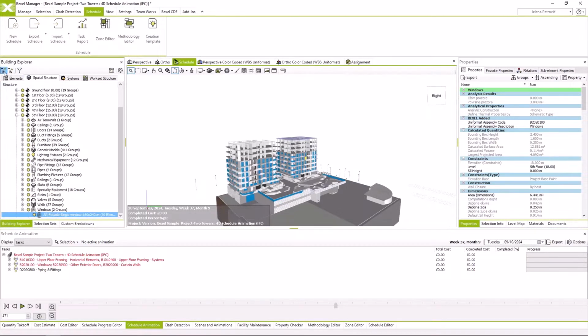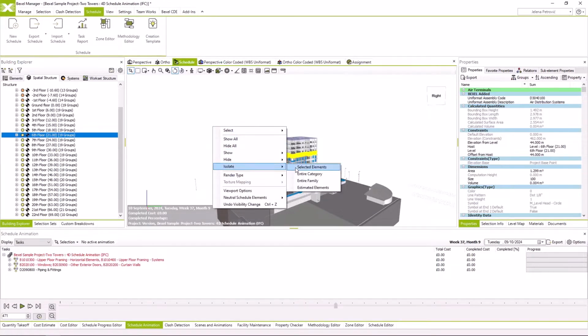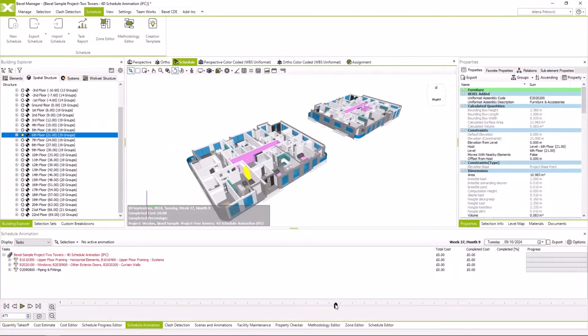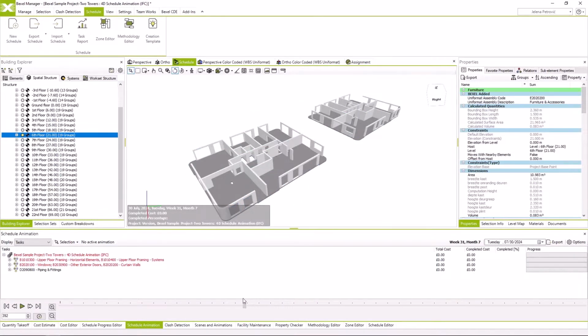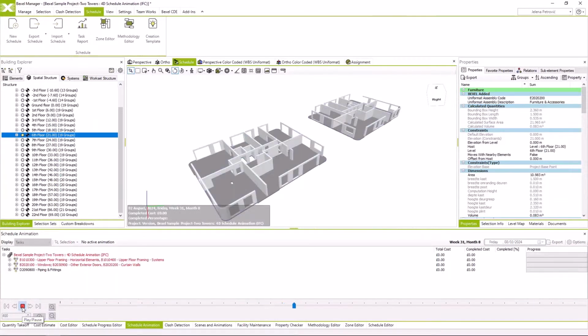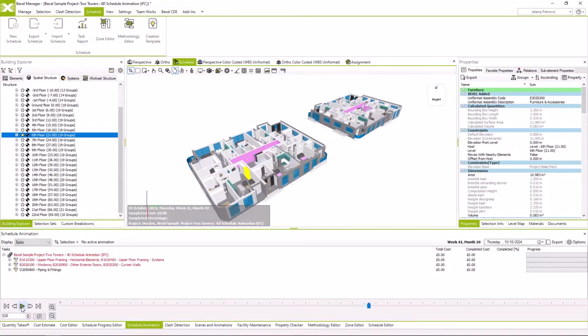Then also, our model is federated from IFC files exported from the Revit authoring tool, so the export settings should be properly defined, or if the export of IFC files is coming from other tools, the properties should also be checked, and we should pay attention that templates are suitable for these models as well. All this will be addressed in some of our next webinars.